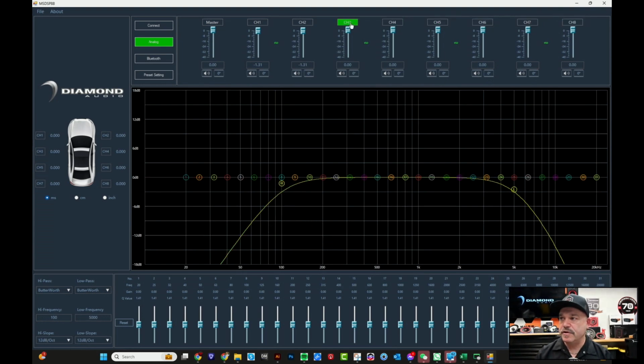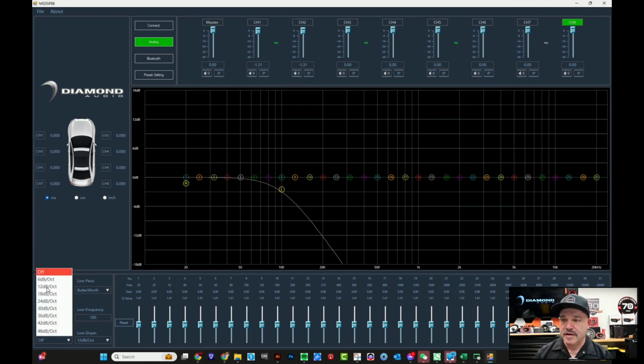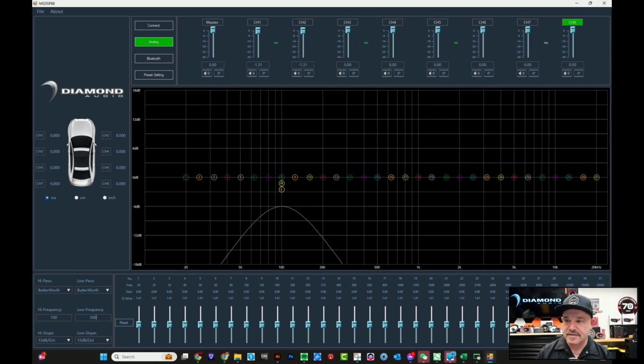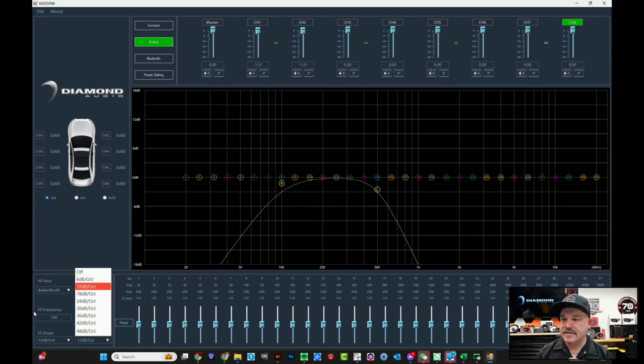It's pretty straightforward. Again, if you needed to do something tweaky, you could disconnect these. Channel 7, let's say, is your subwoofer, and channel 8 maybe a center channel. Then we could do a band pass. Maybe we're going to do 500 hertz. Or I'm sorry, maybe let this roll all the way off at 20K. And then we'll do 500 on the low pass.